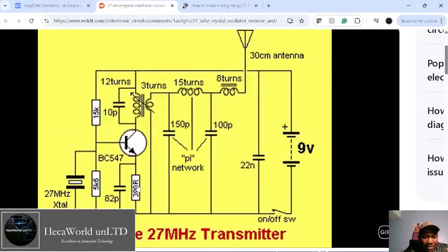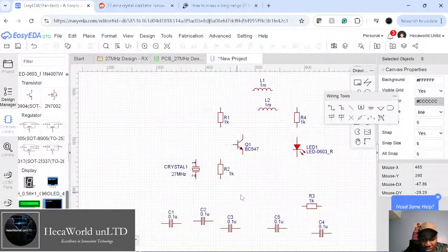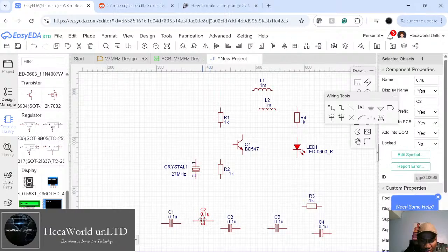So resistor, capacitor, and then capacitor, inductor. We need this kind of transformer inductor. So let's go grab that. So remember, resistor, that'll be R3 and C2 at the base. So C2 here. No, this is at the emitter, sorry, not the base.